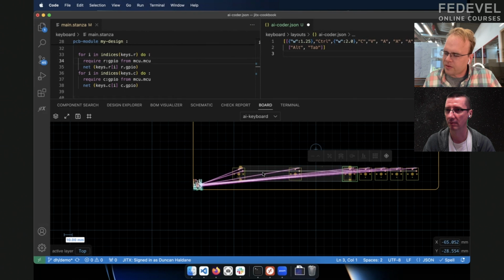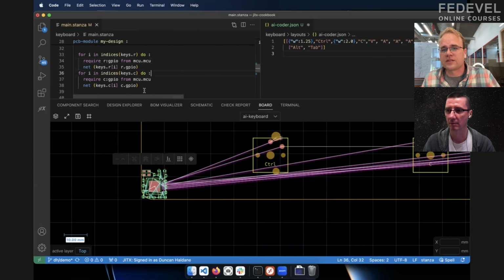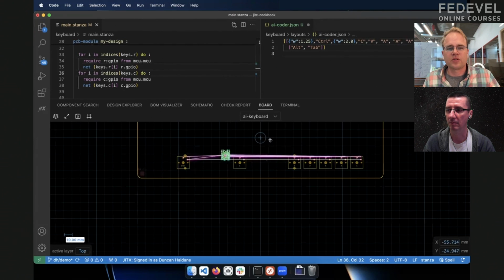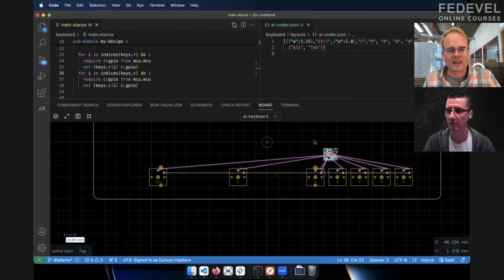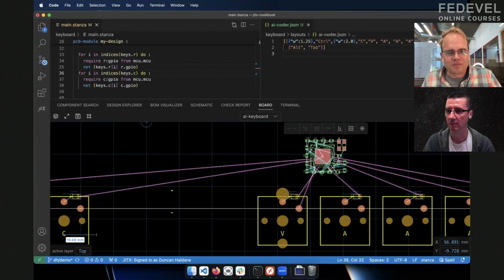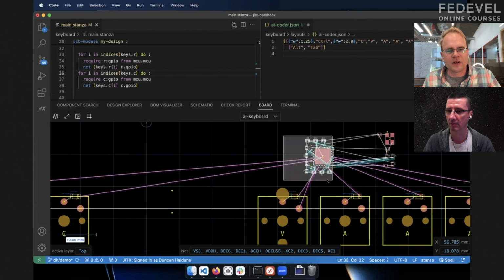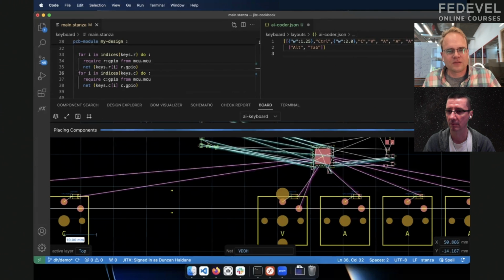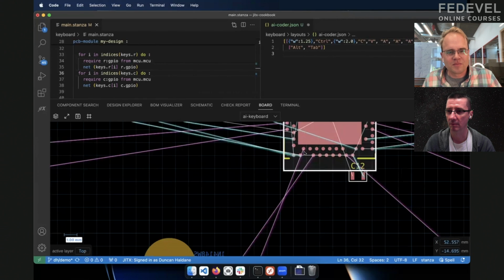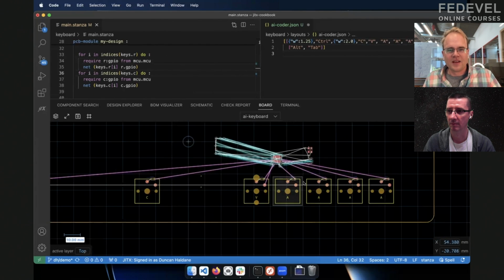We try to build automation so that it just makes your code more powerful, right? The other thing it's doing is I/O assignment for your microcontroller, so you can figure out what I/O pins. Again, it's a little IoT processor here. It's kind of a pain. Half the I/O are assigned to this inner row that's not accessible unless you get fancy vias. But yeah, you can use it to route out.